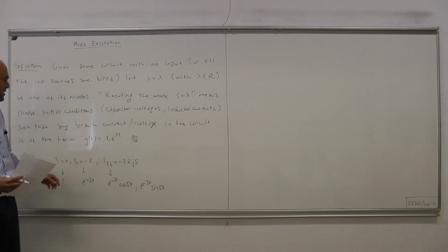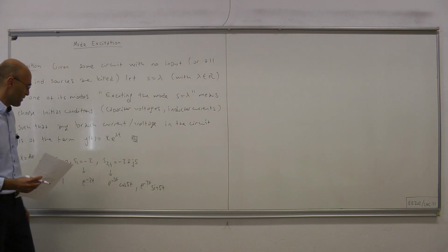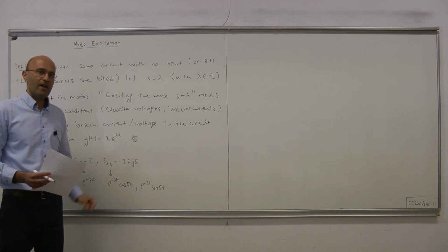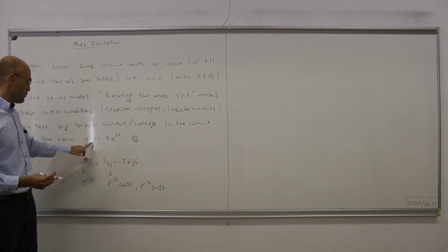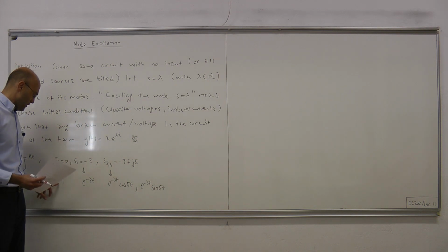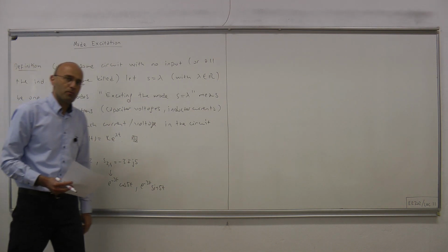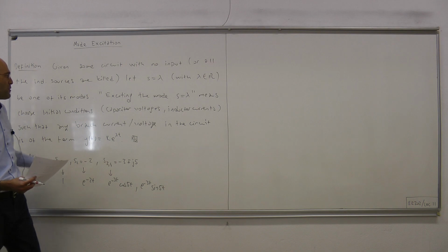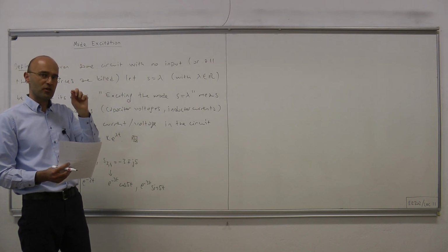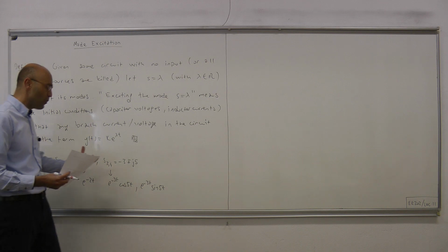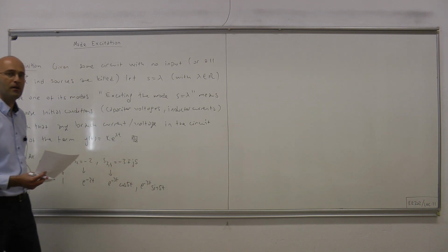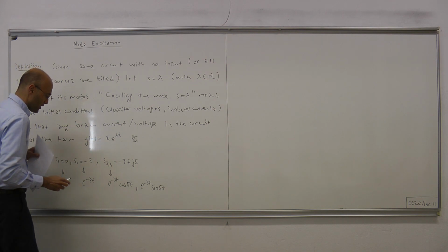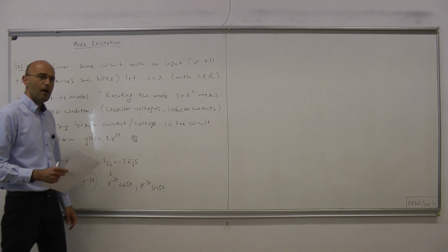So that means for an arbitrary set of initial conditions, you go and check any voltage or current in the circuit, and what you will read is y of t equals a linear combination of those 4 terms. Now, what we want to do with mode excitation is choose the initial conditions very cleverly, so that although in general all these 4 terms will appear in our circuit, we want, for instance, everything throughout the circuit to be something times e to the minus 2t.